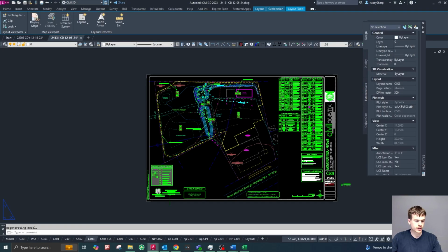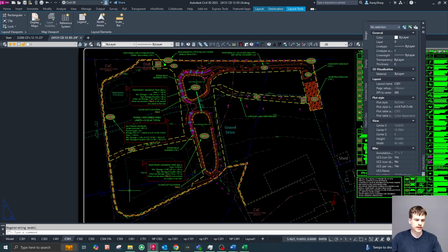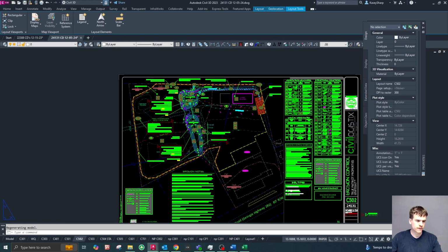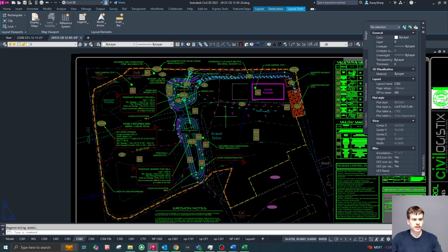Okay, and then if I pull up an erosion control plan here that's already been done, just so we can take a look at it, we'll go to phase 1 to get a general scope of what exactly is going on. Actually, I'll start in phase 2 here. Typically your erosion control plans are designed to direct all of your runoff during construction activities into what's called a sediment trap or a sediment basin.